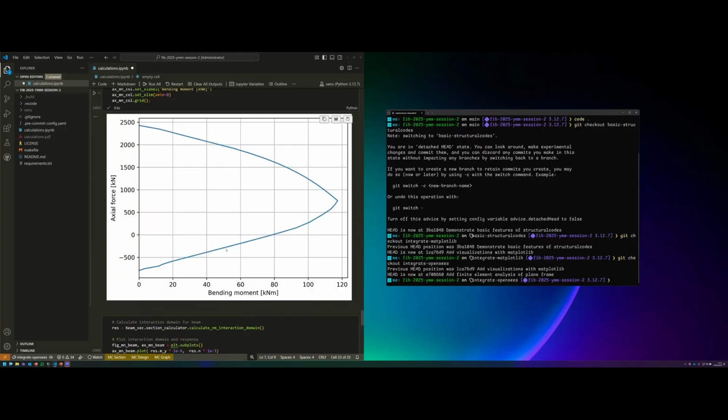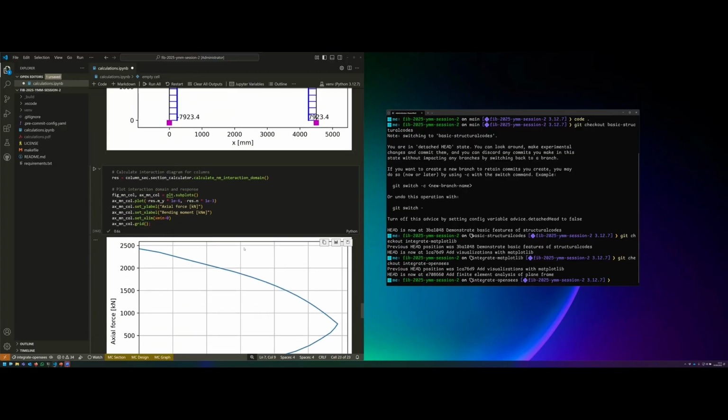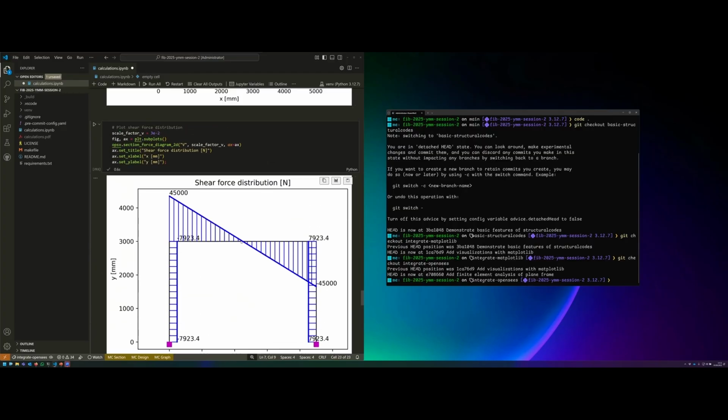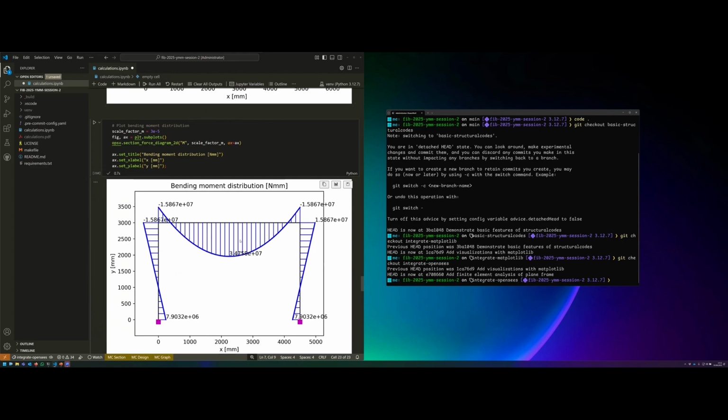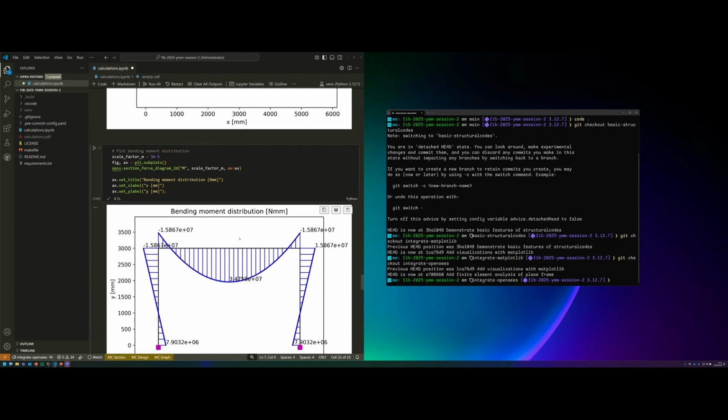So in this stage of the notebook, we used our sections to provide input to OpenSees. Well, you could also think of other options here. So let's say you wanted to perform a stepwise nonlinear analysis. You could also interrupt OpenSees, then change material behavior depending on the response that you had recorded, etc. All from within this Jupyter notebook. But this is perhaps the simplest way to interact with the system.